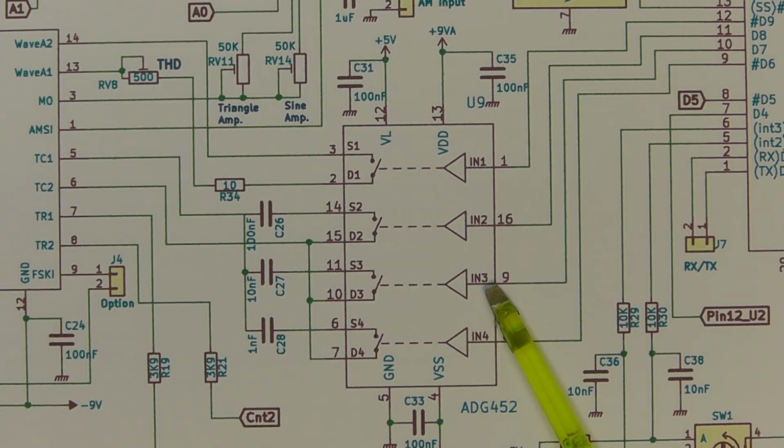Here you can see in the center we've got an IC which has got 4 logic switches in there, 4 analog switches. This is actually the Analog Devices ADG452 IC. The reason I chose this particular switching IC is its on resistance is very low at only 5 ohms, and that's exactly what we want when we're switching in our timing capacitors. So you can see here that we've got 3 capacitors, and these are the ones that we will switch across pins 5 and 6 of the function generator IC to choose the frequency range.